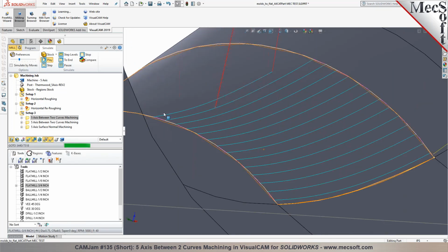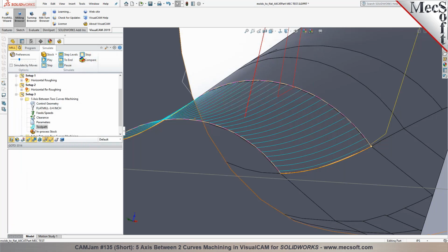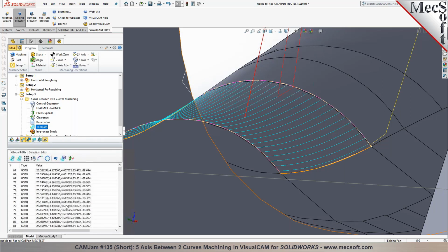So it's literally having to unwind itself right now? Yeah, it's doing an unwind in certain areas because you're putting a primary axis limit of 0 to 360. And it just happens to want to be in between the whole time. If you take a look here, you'll see the angles that are being computed. The angles are actually computed right in here for you. Every unwind is marked in the toolpath, so you will see that happening. When it sees an unwind, it automatically retracts to a safe clearance so the head can tilt.